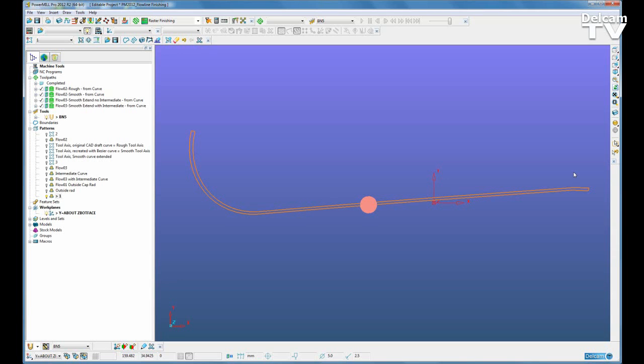2 segments are the drive curves, which dictate the start and end passes, and 2 segments are for the limit curves, which limit the length of the passes. Together, they should form a closed box containing the region to be machined. There is an additional option to include an intermediate curve between the drive curves as an additional method to control the blending between them.